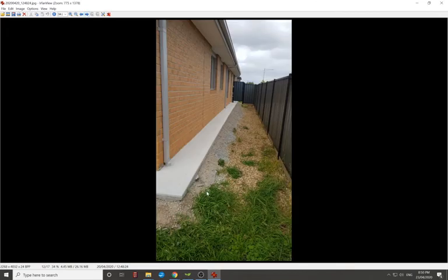Now we go back this way. Okay, all right. So yeah, you've got the spilled up concrete against there. There's no fault lines in it. There's no expansion against the wall of the house. And it's pretty straight. It's a little bit kinked just here. A little bit of varying thickness on the edge. Yeah, so it's functional, but it's far from good.